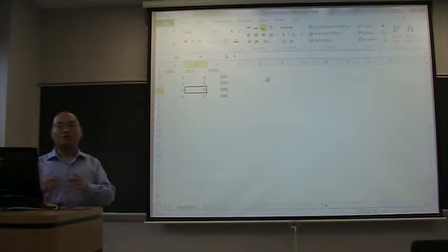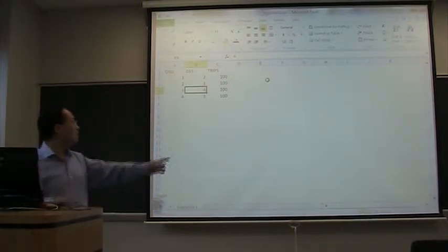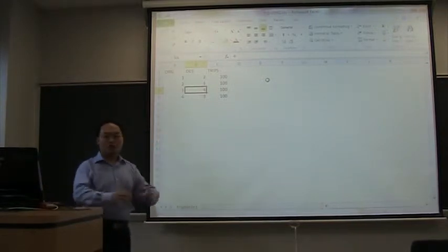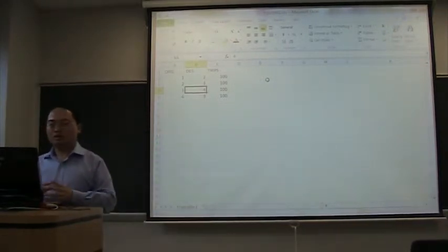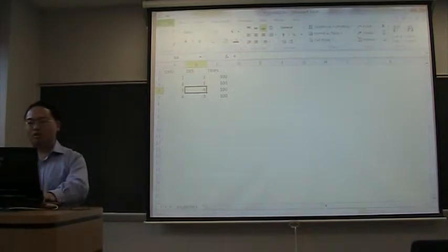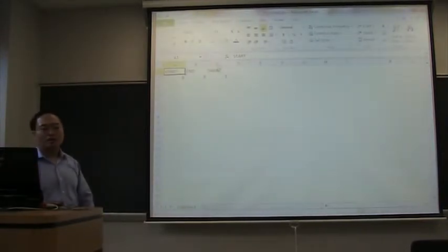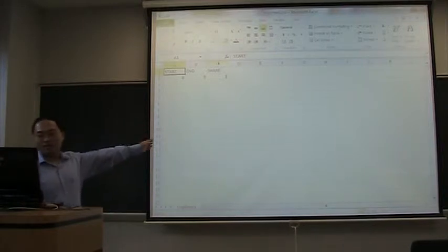And in this step, I'm going to show you how to convert this OD table or trip table into the format that TRANSIMS requires. So we use a tool called convert trips. The input will be this OD matrix. And another one is called trip time. This is very easy to understand.